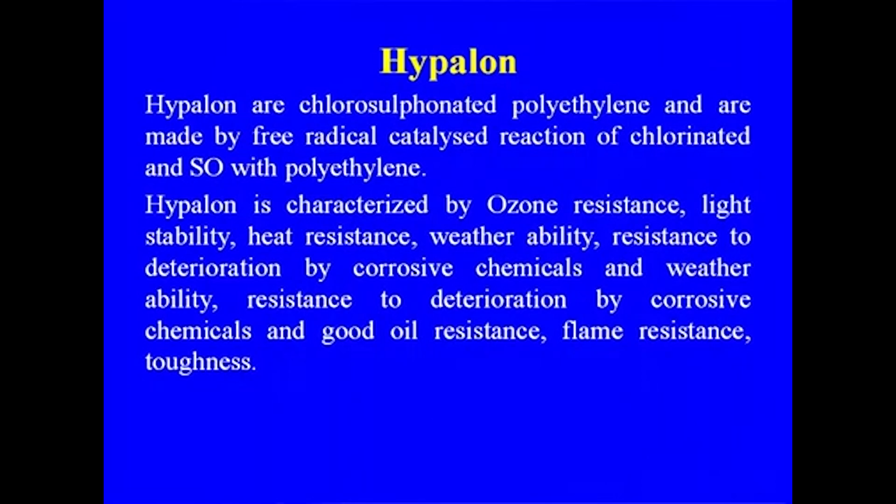Another class of the synthetic rubber is the hypalon. Hypalon are the chlorosulfonated polyethylene and are made by free radical catalyzed reaction of the chlorine and SO2 with polyethylene.